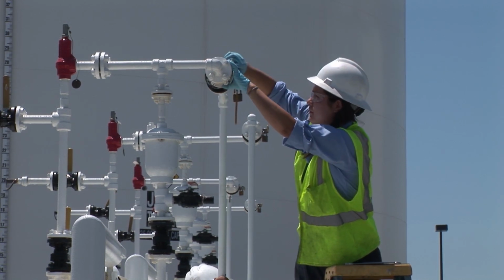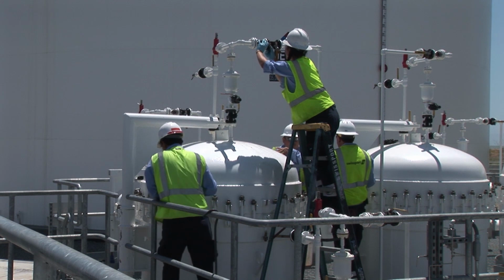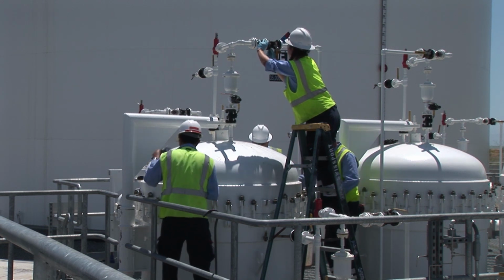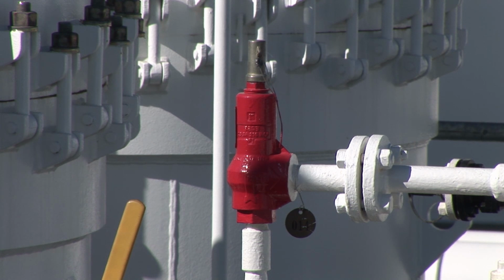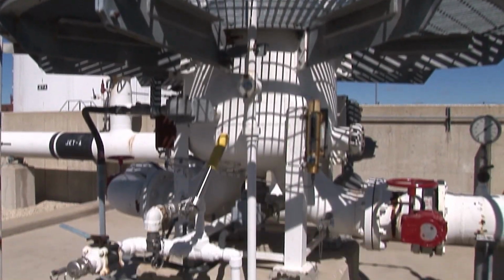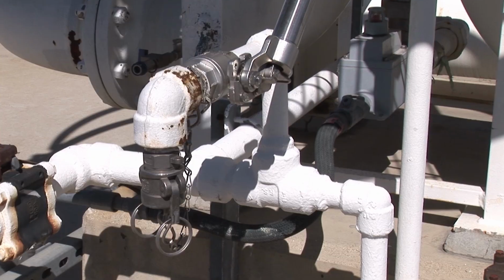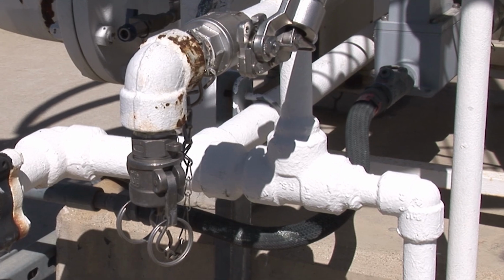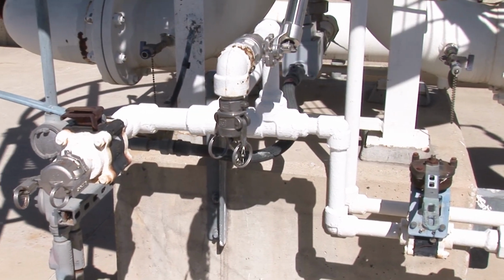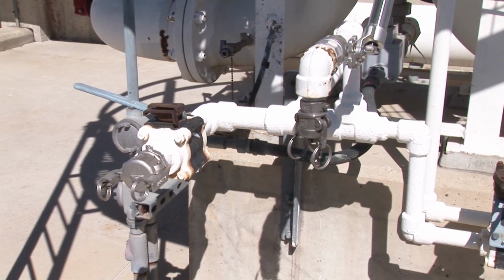This air eliminator with check valve eliminates air during filling and prevents air from re-entering the vessel during operation. This pressure relief valve ensures that the maximum pressure of the housing is never exceeded. Each housing is fitted with two manual drain valves. One is for draining accumulated water from the vessel, while the other is a product drain valve that allows product drainage from the housing and inlet and outlet chambers.